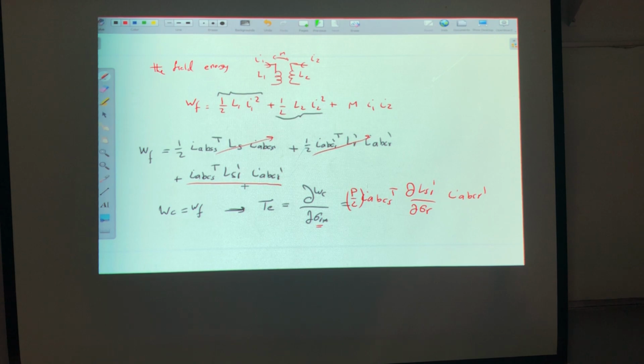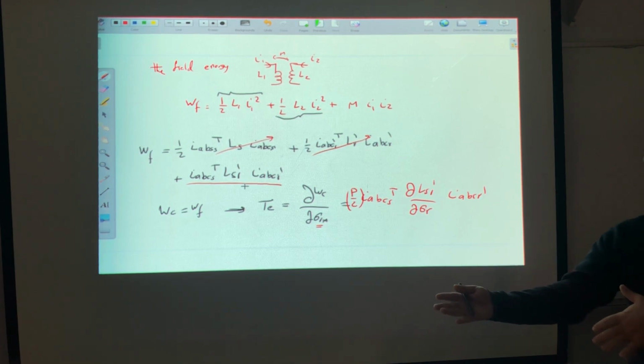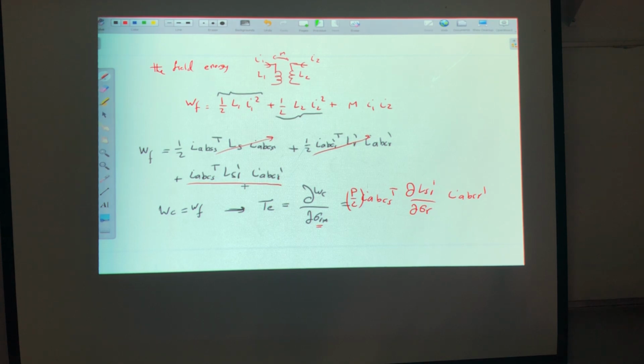So in the end of the day, I need a mechanism, a transformation, in order to simplify the understanding and the control. This means I need a certain transformation in the same concept as Laplace. Not Laplace, of course, but Laplace found a method to transfer a differential equation to an algebraic equation. Here, we will have another transformation in order to transfer a time varying system to a time invariant system.